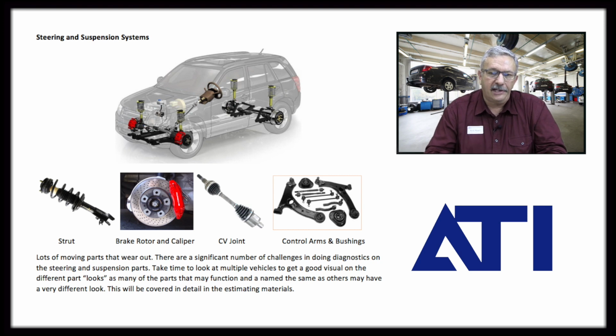So when you're doing your estimating processes and preparing your repair plan, the things you want to look out for are excessive tire wear. Let's say somebody just had an accident and the car had to be towed to you, but I see cupping conditions on the tires. That will tell you that that car had a pre-existing problem before the loss. That's something you have to document, because you're going to be fixing something that wasn't part of the accident. It was actually a maintenance issue. In reality, the customer owes for maintenance issues, separate from the impact issues.